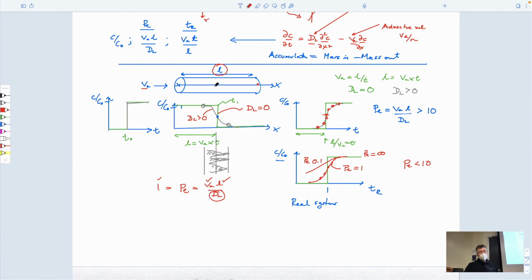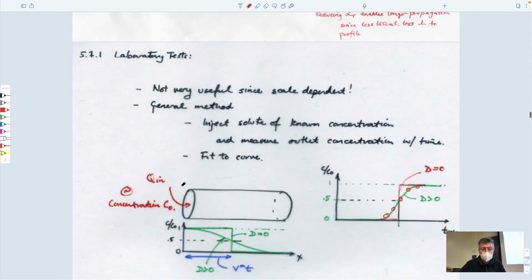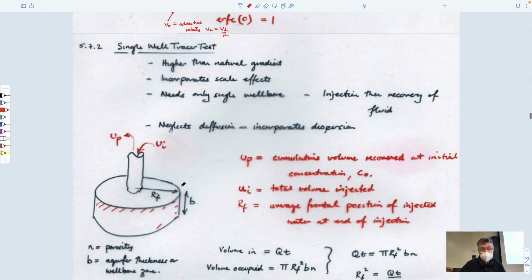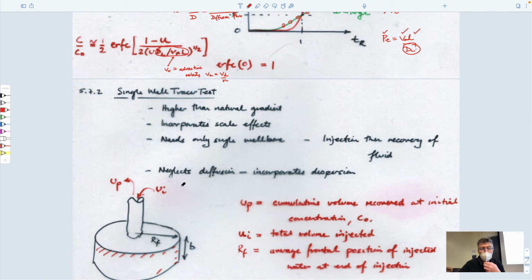What they are useful for is if you are storing low-level radioactive waste in a clay barrier, and the only mechanism by which the radioactive components can get through is by diffusion, no advection but by diffusion. Then your experiment will give you exactly the right answers because it's representing the real behavior that you have. But if you want to represent advective fluxes, it won't be very useful for you. So scale is important, and the whole essence of that behavior is related to scale.